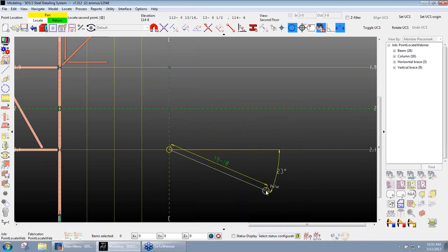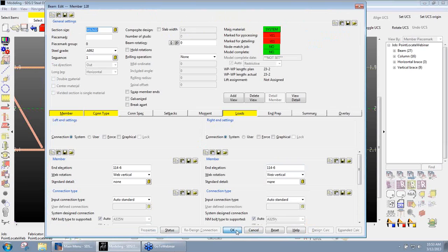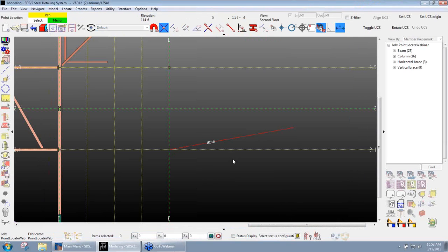Now, you can, again, still type in your degree here. So if I type in 15, it's still snapping to that 15 degrees, and that's what's going to get snapped to unless I clear that out. That can be pretty handy there. Okay, remember if polar is not turned on, we don't see the degree increment on our screen, but you can still type in 15 if polar is not turned on to get a specific degree there.